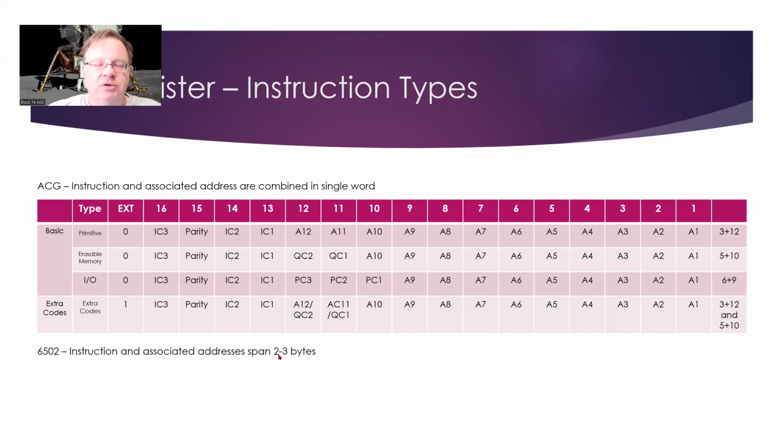If you want to do what they call the zero page, which is the low 8 bits of memory, you can get by with just 2 bytes. One byte is the add instruction, and the second byte is which address in the zero page you're going to apply that add instruction to. Or if you want to do a full 16-bit address, you have 8 bits for the opcode and then another 2 8 bits to store that 16-bit address, so a total of 3 bytes.